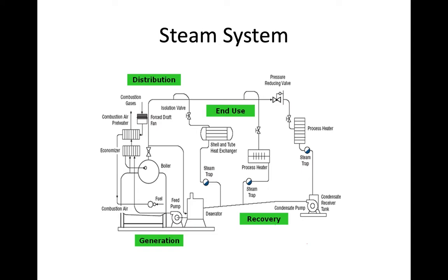So we try to recover 100% of this condensate to flow back into the boiler, returning to the boiler. If we can return all of this condensate, we can save in many aspects.